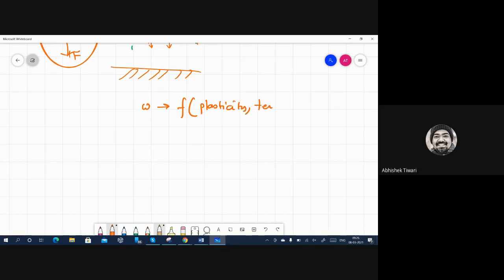Of course, the effect of temperature will be there, but temperature can be reproduced in the model by the stress strain diagram. The stress and true strain values we give, these stress strain points in the model, should be at the temperature we want to simulate. So we conduct a tensile test at that test temperature, take the stress strain values from that experiment, change them to true stress and plastic strain, and then put them in the model. Then the temperature effect is already there.